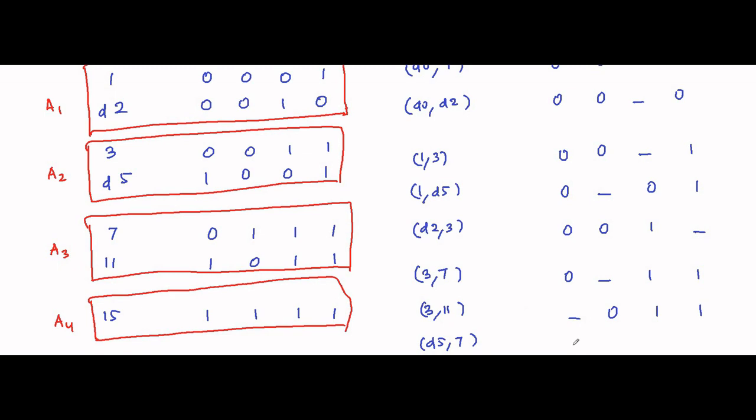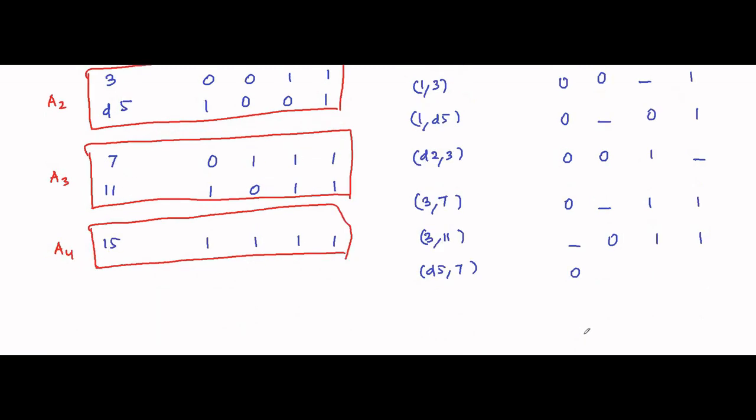But when you are getting started with this, it's best that you compare them one by one. When you practice more, you get habituated and acquire this ability to form minterm pairs just by comparing the bit positions in your mind. So 0 1 dash 1 is the pair between groups A2 and A3.